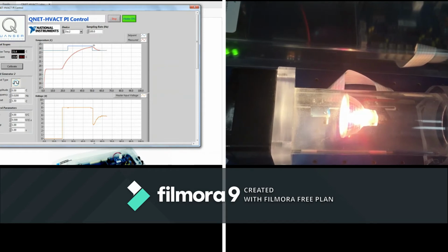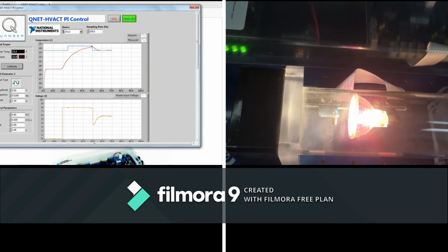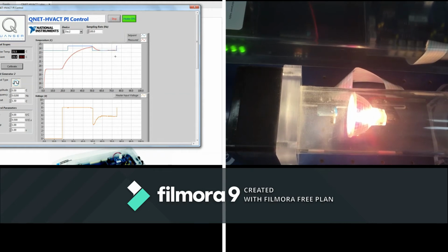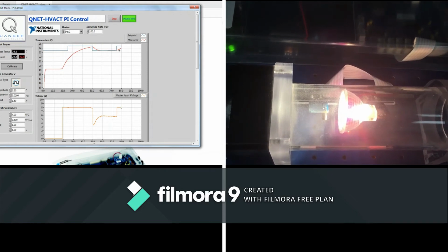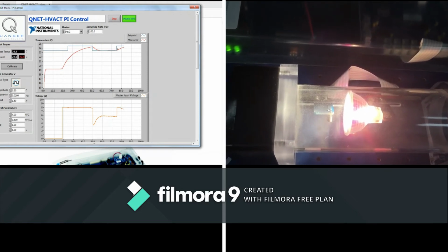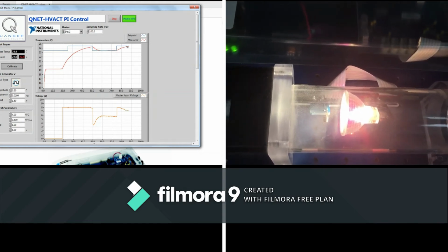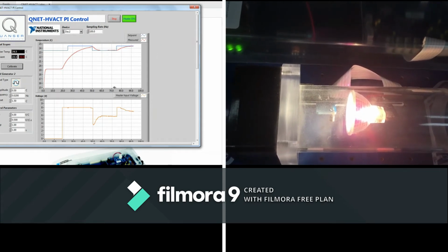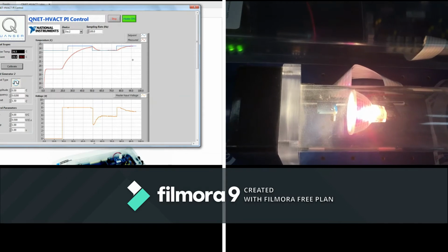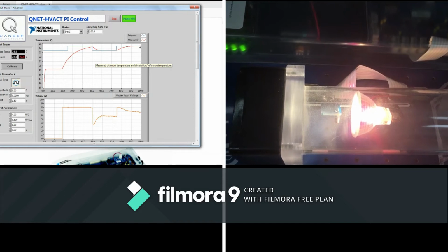The square wave has changed now, and we are following the low temperature, which is easy to follow because we already have a higher temperature. So the new cycle will start. This is the new cycle, but our actual temperature has some delay. It cannot follow immediately with the rise. With a delay, it will catch this signal, maybe from 70 to 90, about 15 seconds. So now we are good with the same signal, with the same temperature, until we have the new cycle.